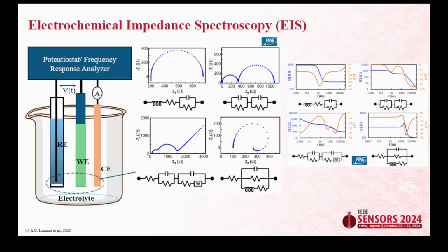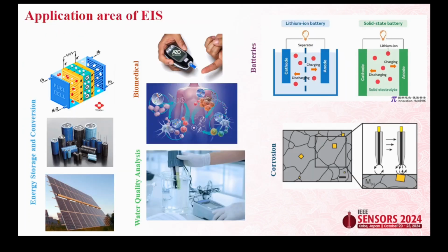So for most sensing applications, the rule of thumb for us was that the area of the counter electrode should be double the area of the working electrode. That does not mean we have to increase the size. This is why we are now coming up with spiral models or spring-like structures for counter electrodes that we can use. So the effective area for the collection of the current or the charge should be double that of the working electrode.